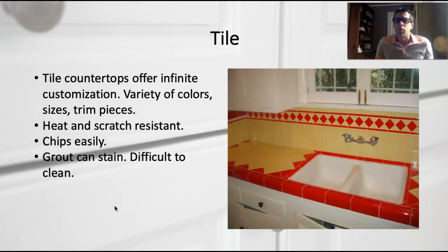The grout is very porous, and if it's not sealed with something, dirt and water will get into it, and mold will start to grow on it. So it has to be maintained, and if it wasn't maintained, it's going to change color and be difficult to clean. And every now and then, you're just going to need to re-grout that material.